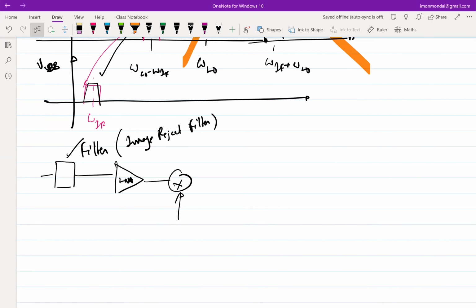Yeah, right. So it gives you an additional set of filtering, right? So fine, I understand some filtering comes from maybe a SAW filter upfront and all, but it gives you some additional level of filtering. And it's a linear block, right? Ideally in your signal chain, you would want the linear blocks to be upfront, so that the nonlinear blocks do not see a lot of signal swing, right?